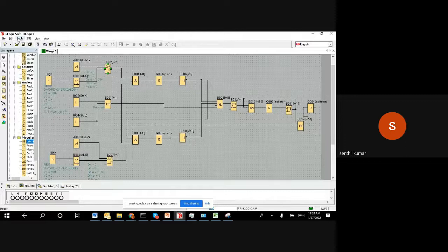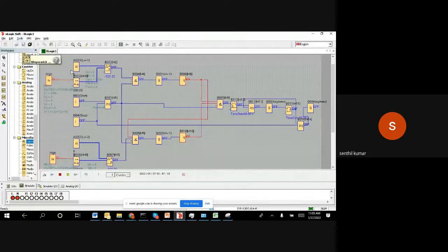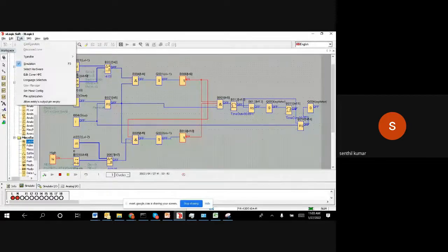We will go for simulation and check what it is giving. Right now the bottom is 500, and it's giving minus 500. If I simulate 1000, let us say 1000 is on, it is there actually. Slowly, when it comes below 500, it's supposed to go off. I just want to test it, to make sure my logic is right. Yeah, it's going off, so it's correct actually.